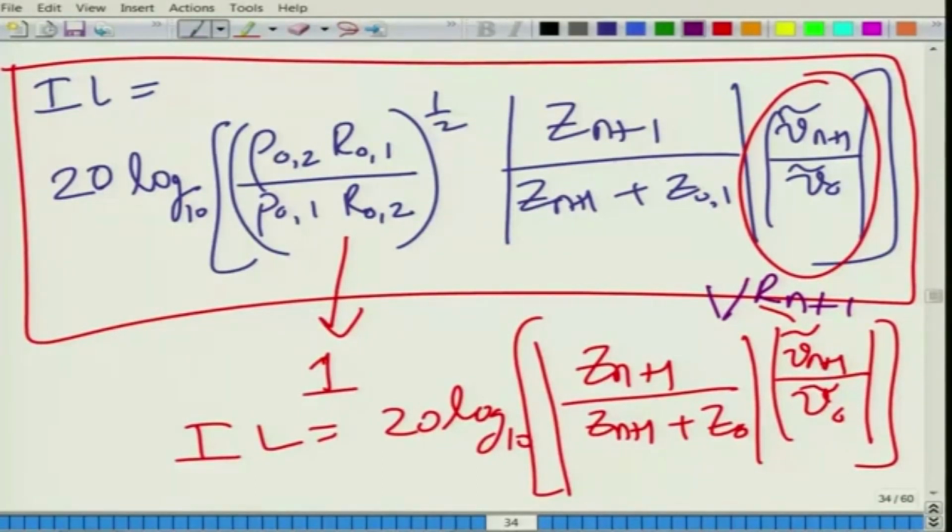I am saying hypothetical because, as the hot gases flow out of the exhaust system, their temperature drops. But most of the analysis in mufflers is carried out for zero temperature gradient. We assume a constant or uniform sound speed. If you recall, sound speed was root over gamma times R naught into temperature in the absolute Kelvin scale.